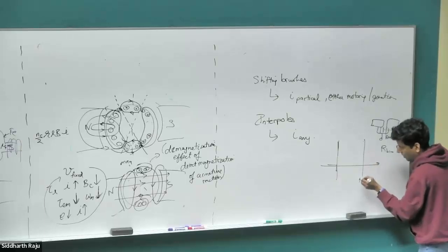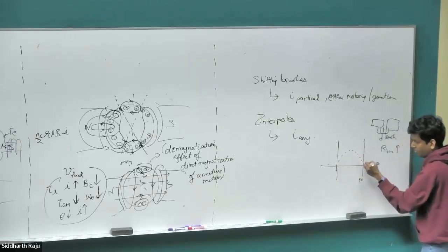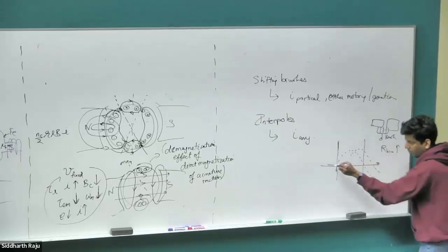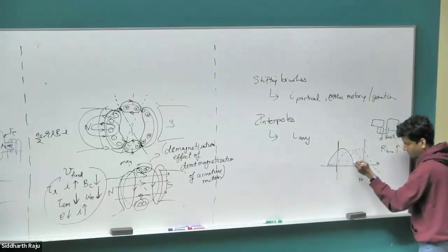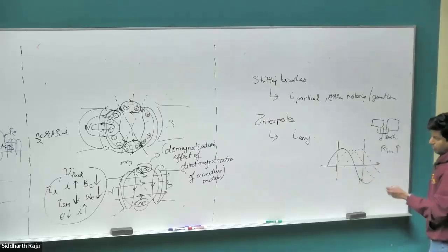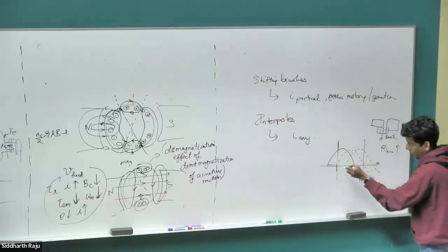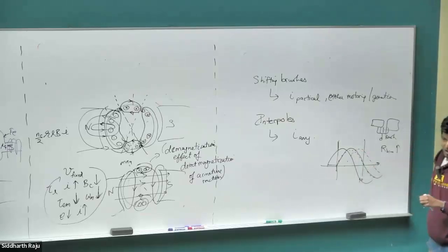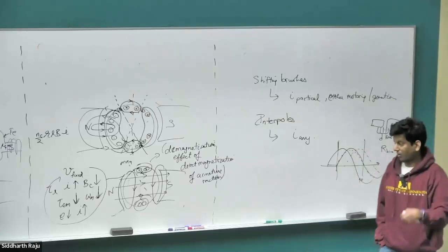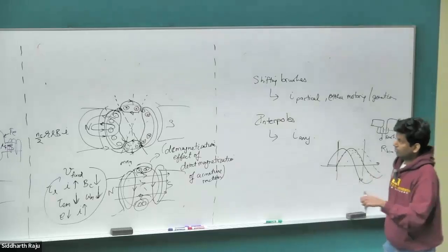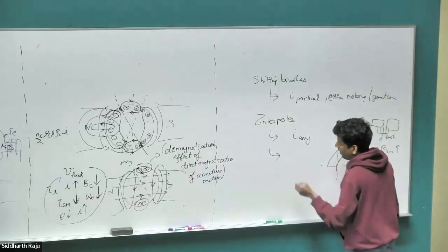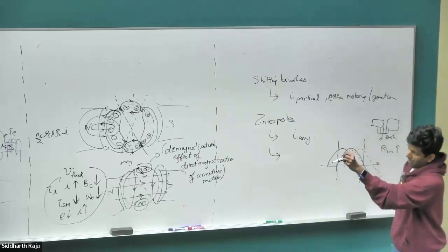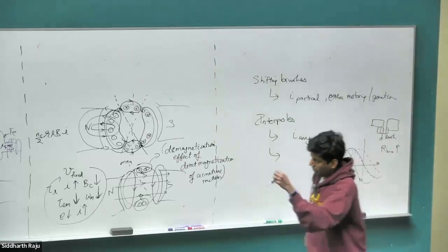So let's say this is my 90-degree point. This was initially my voltage, and this was my current. Now, if I shift the voltage back so that it goes zero at much earlier point, then the current would also be shifted so that we can get it to go back to 0 degree at a much earlier point, at the desired point that we need. So this is what interpoles can let us do, because not only can we compensate for the armature reaction, we can in fact make it go a little bit further down.